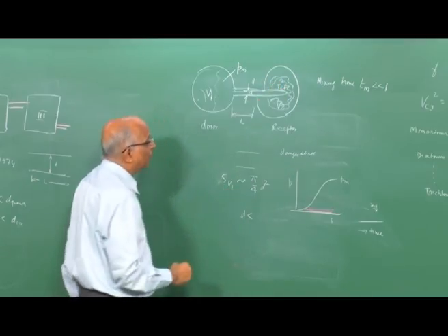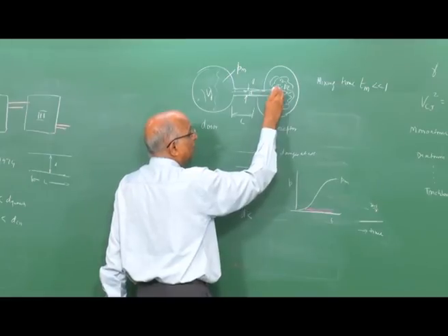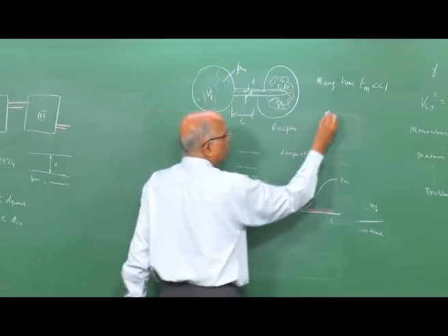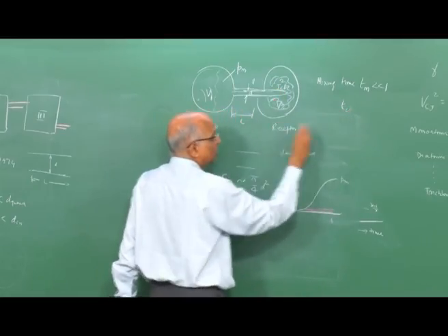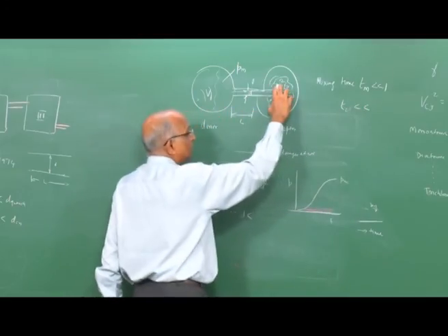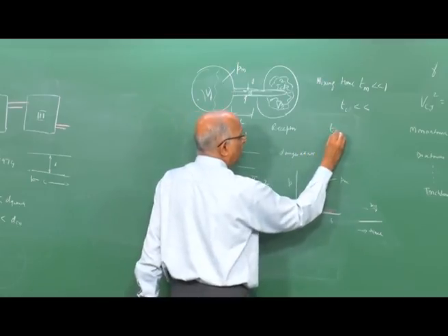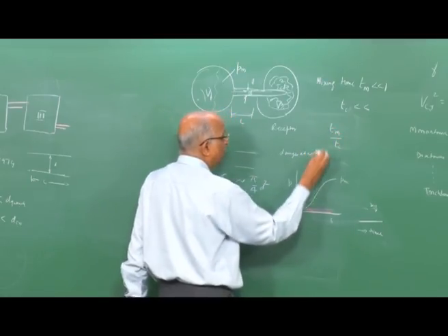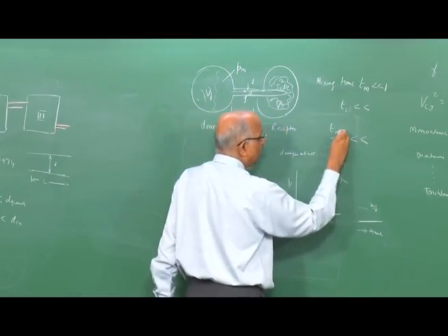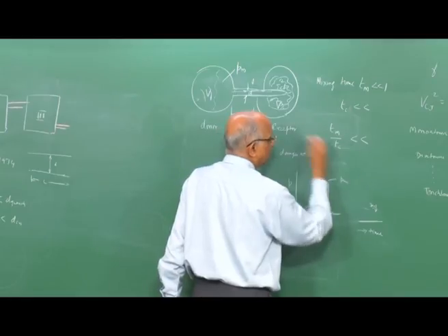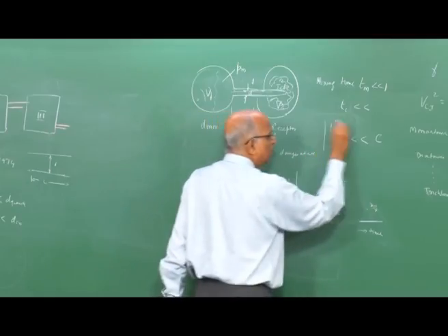because it gets quenched. However, if the hot jet comes and the chemical reactions occur so rapidly that heat is getting generated, well, this also explodes, or rather, if the chemical reaction time, let us say Tc, of the gases here is a small number, well, this container or reactor explodes. Therefore, we find the ratio of Tm by Tc. If the mixing time is small, well, I am safe. Therefore, for safety, I say that the mixing time divided by the chemical reaction time must be less than a particular value, and this also therefore becomes an important parameter.